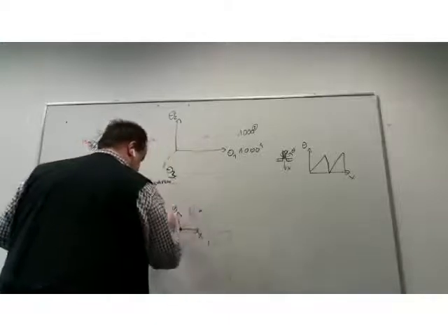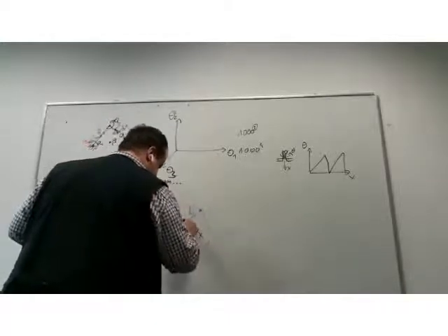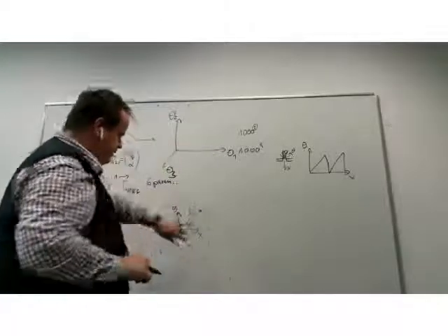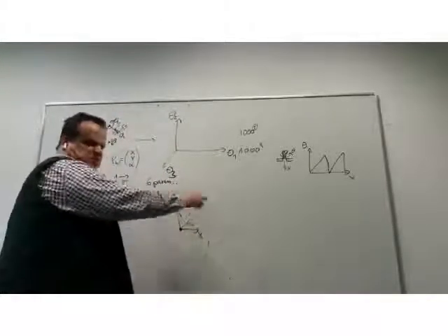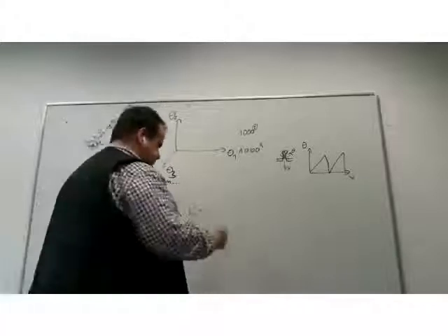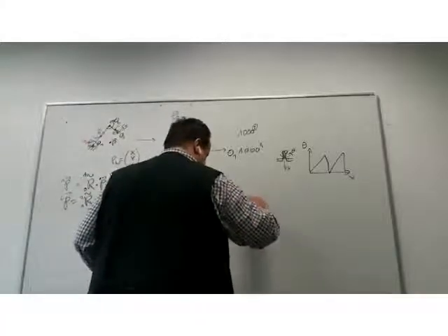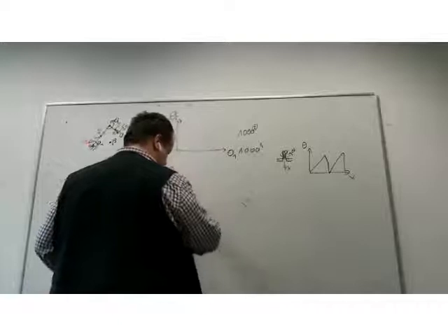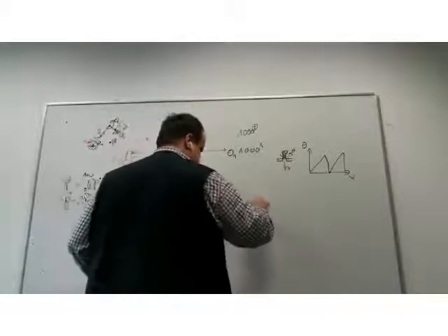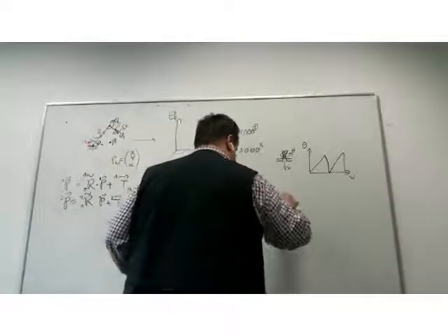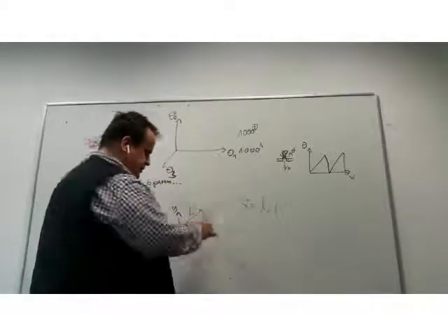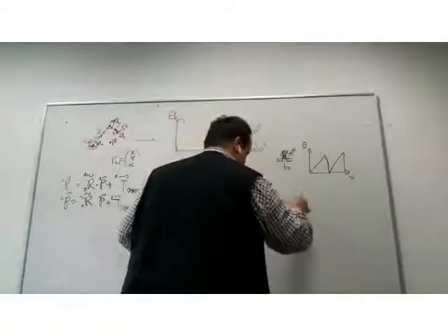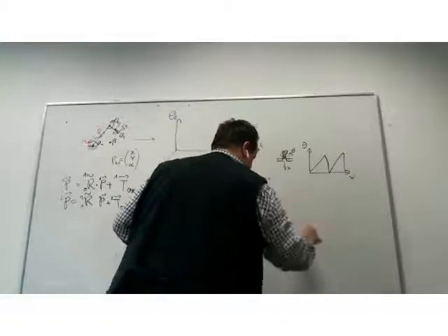And my theta 1 can move the second joint on the circle. So the x on the circle is nothing else but L1 times... if theta is 0, then I'm here, then it's just x.